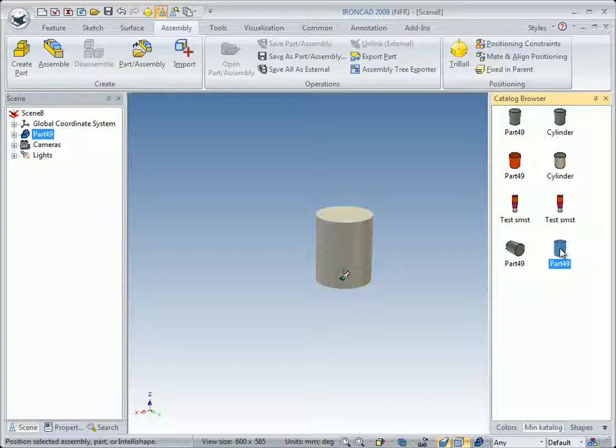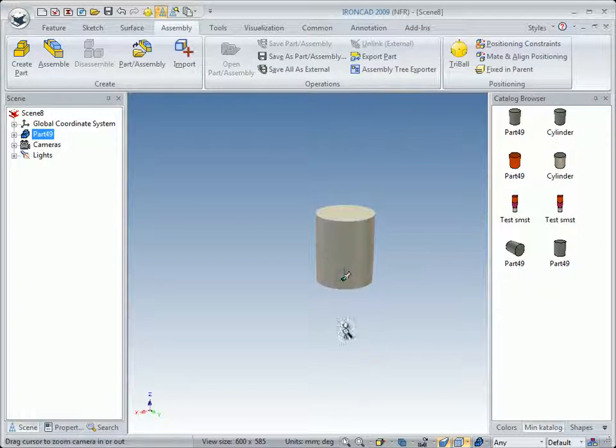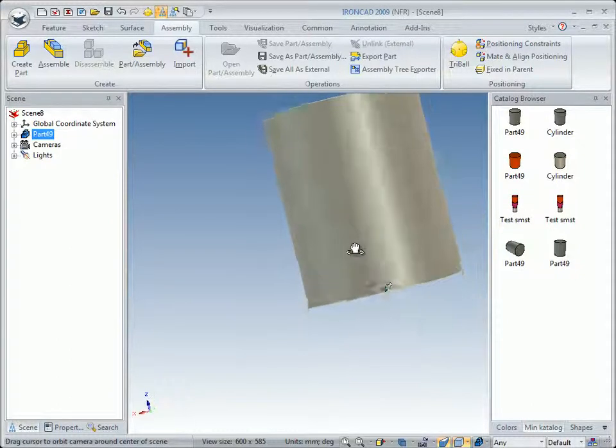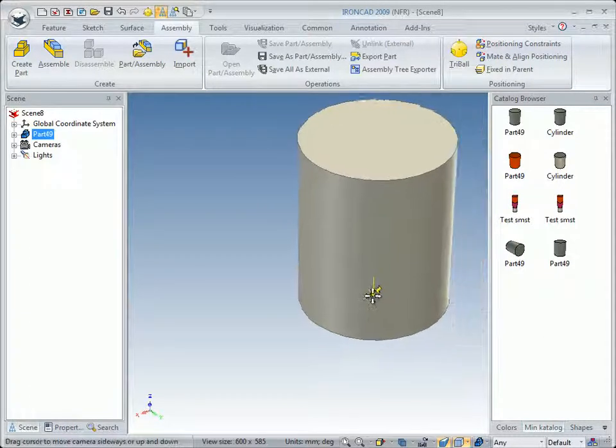And if we drag this one where the anchor is set to disallow drag and drop it in the scene, it will be placed as the other one. So we select it and delete it. So if you want a part to be placed in the scene as you see it in the catalog, you have to change the anchor into the right position. So we will select this part we have in the scene, and we will do a test on this one. We will change the position of the anchor, that one, and we select it.